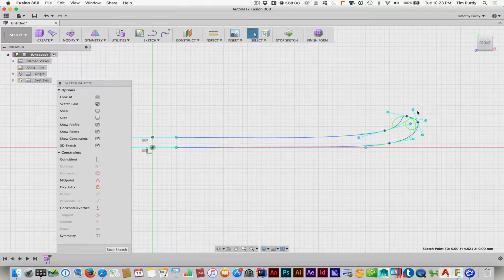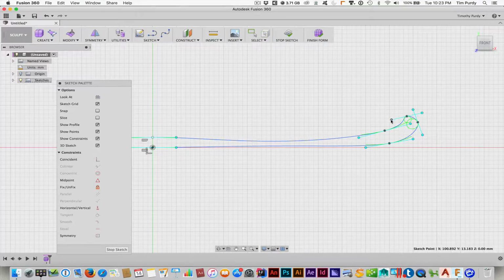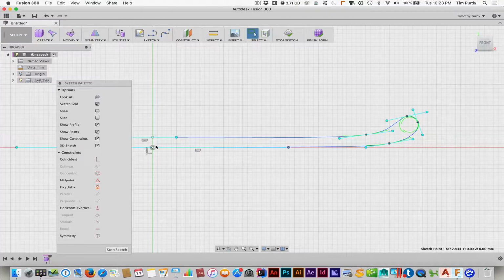That's looking good. Everything's working except that little corner right there is very sharp. So let's see if we can sculpt it. Maybe if I grab this point, pull it over, that'll smooth out that edge. That looks good. And then I'll pull this back up to get a more planar setup. Now if I want this to be planar further out, I can grab this handle and pull that out. Notice that will continue that implied tangent out further, keeps it flat basically. Okay, not bad. We'll finish this sketch.